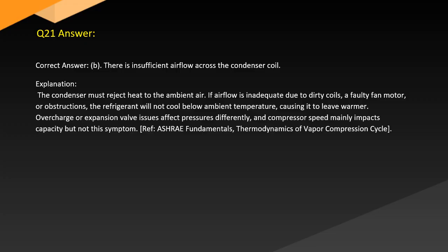Answer. Correct answer: B. There is insufficient airflow across the condenser coil. Explanation. The condenser must reject heat to the ambient air. If airflow is inadequate due to dirty coils, a faulty fan motor, or obstructions, the refrigerant will not cool below ambient temperature, causing it to leave warmer.